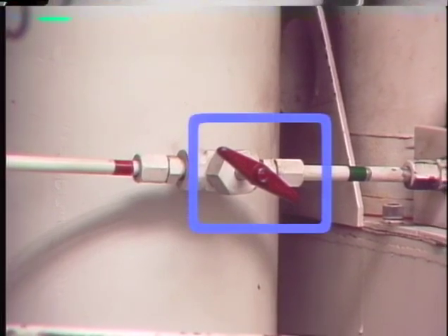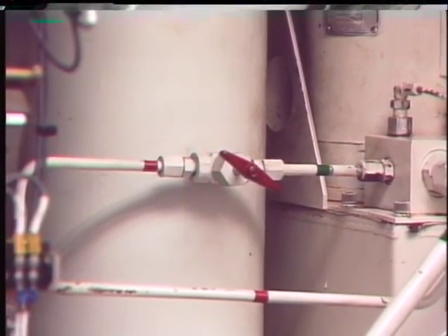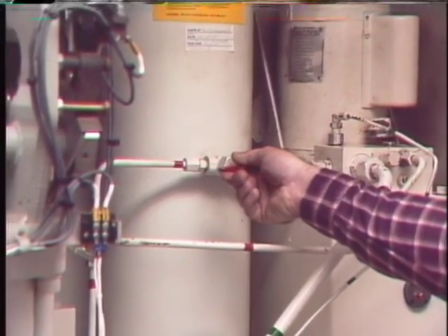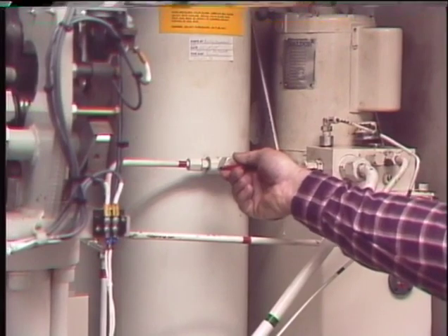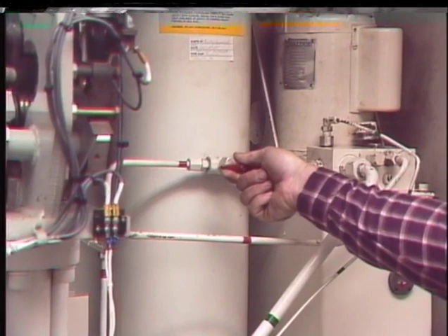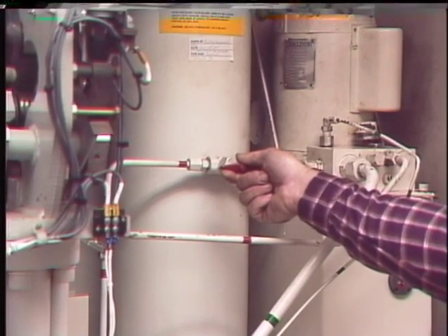Then a pressure bleed valve is partially opened to slowly bleed pressurized fluid into the low-pressure reservoir and reduce system pressure to zero. The valve is only opened part way, and it is closed from time to time to keep the fluid from foaming in the low-pressure reservoir. When system pressure is at zero, the bleed valve is closed and a fluid level check is made.